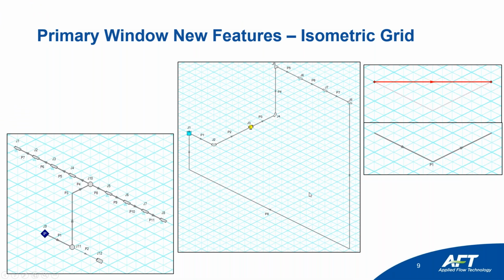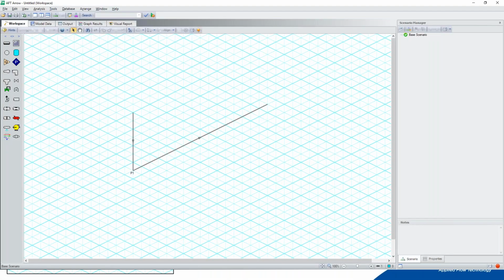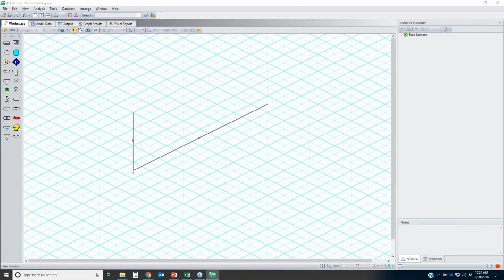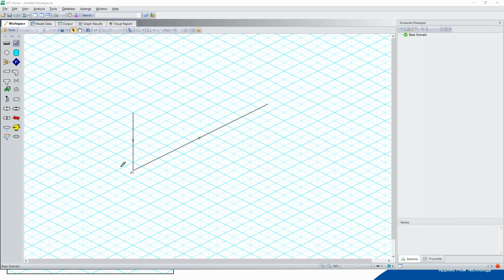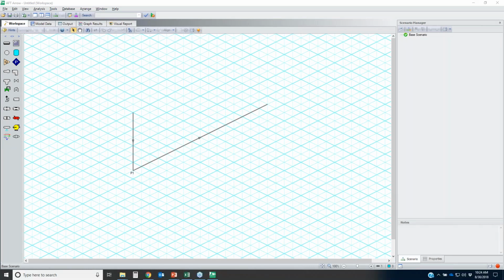So, and we're engineers, we like things to look nice. So here's how this looks. If I wanted to put an elbow right here, what I can do is go back to my normal drawing mode, grab the elbow, hold the shift key down, and split that pipe. Well, it's not going to let me do it. But anyway, there's my new elbow.